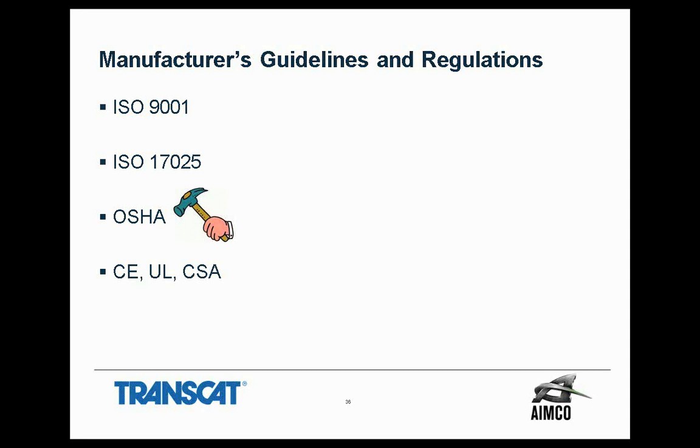Suzlon last month just brought in and trained 24 OSHA reps on the environments that wind turbine techs work in. So we'll start to see OSHA's presence more and more over the next few years. And before everybody goes running for the hills, keep in mind this could be pretty beneficial too. On the typical preventive maintenance on a turbine, you're checking 400 bolts a quarter, 1,600 a year. As Mike alluded to a little bit, North American structural engineers typically frown on retorquing or reapplying the load over time, multiple times, something that we differ a little bit from the Europeans on, because there have been studies that show that it doesn't lead to elasticity and decreasing tension. So the federal oversight coming in could be beneficial on our side, because right now, again, we're working off European standards.